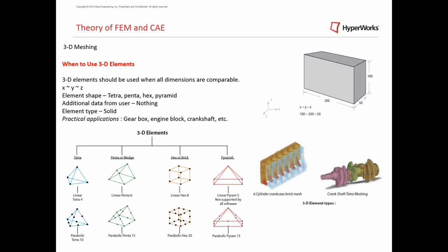3D elements should be used when all the 3 dimensions are comparable. Element shapes are tetra, penta, hexa and pyramid. Additional data from the user is nothing. Element type is solid. Practical applications are gearbox, engine block, crankshaft, etc.